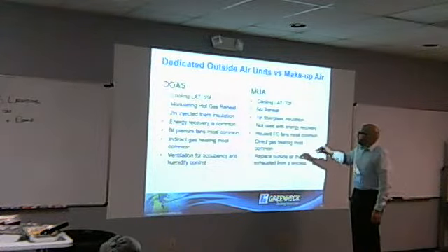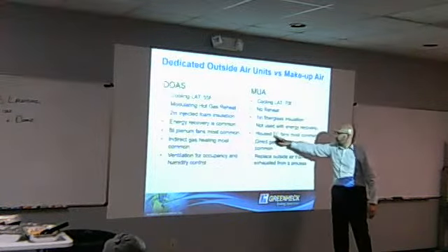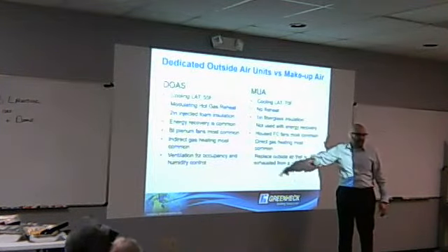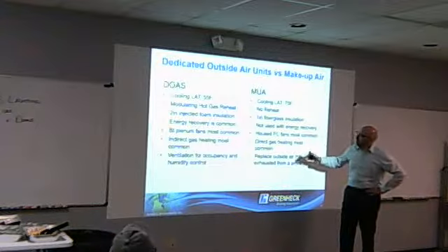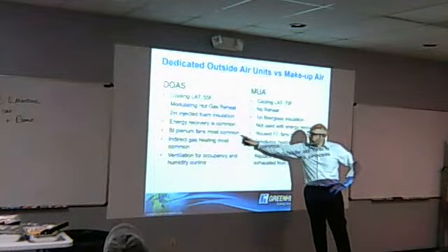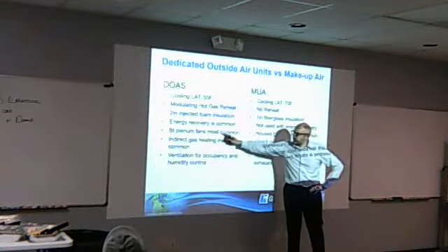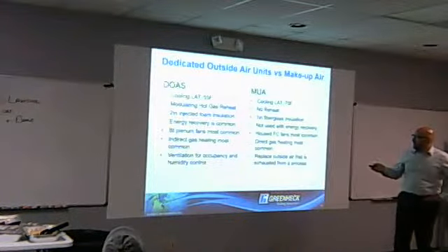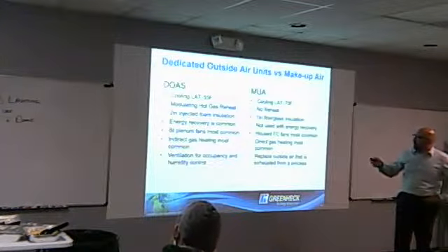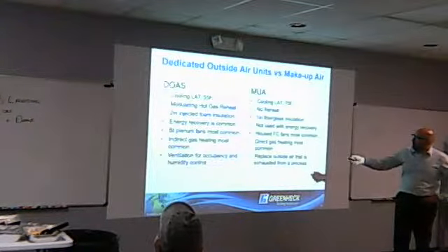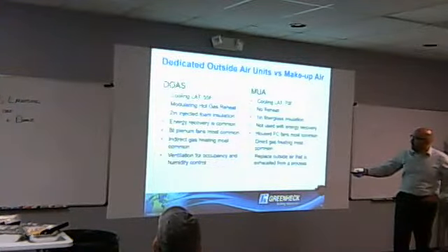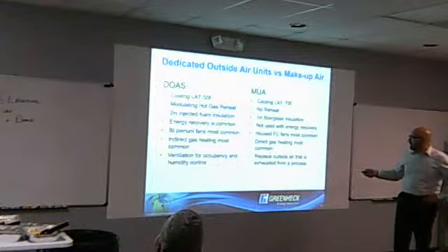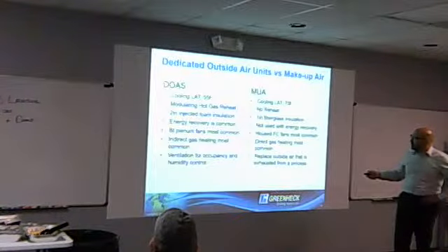We still, and I'm not sure I even agree with this statement anymore. How's forward curve, just from what we talked about already. I think we've seen more movement to that mixed flow wheel. Backward inclined plenum fans, we've seen more movement of these, even away from those into the mixed flow wheel because of efficiency. Indirect gas heating, most common because again, we don't want our dedicated outdoor air coming in with direct gas and products of combustion. So we use indirect gas. Makeup air, not so big of a deal, direct gas.